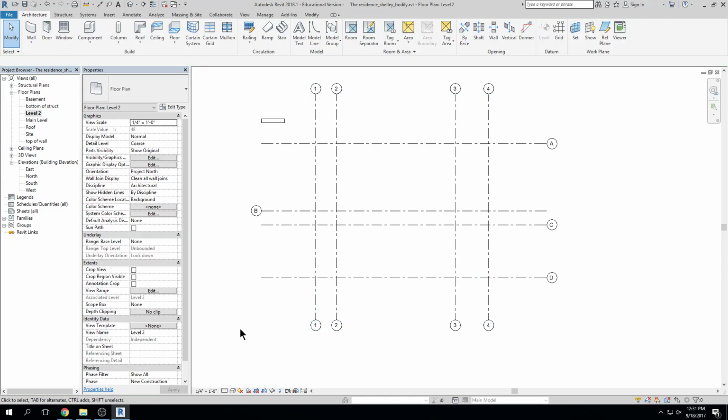All right, one thing that will help you draw this. Number one, use the grids, right? Your walls are going to want to be in the same place on the upper level and the lower level in general. I'll say that as a general good statement, right? When you bring your CAD file in, if your CAD file comes in and it's not in the exact same spot as your lower level one, you can move it, okay?